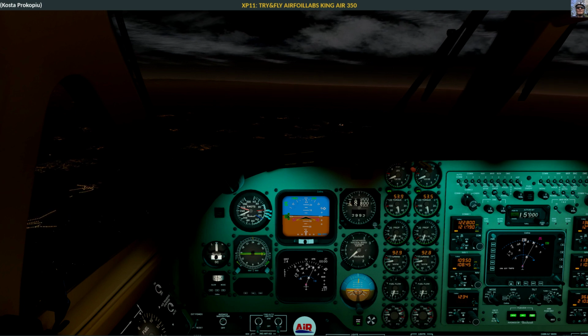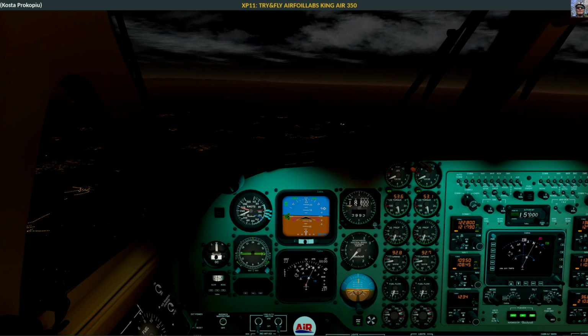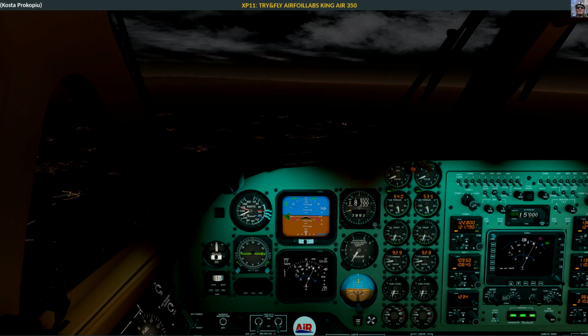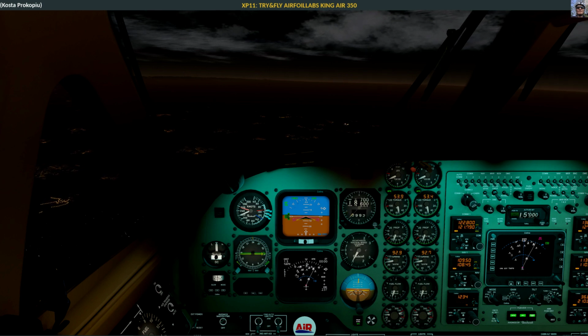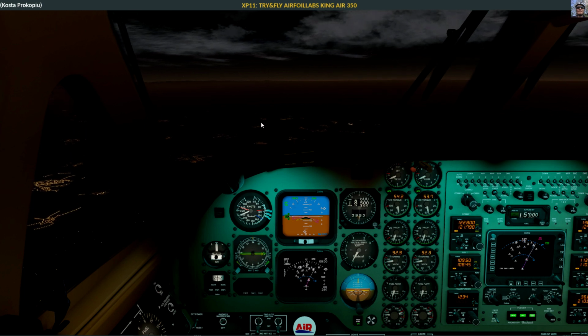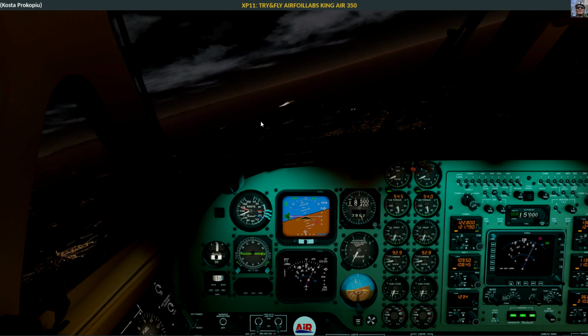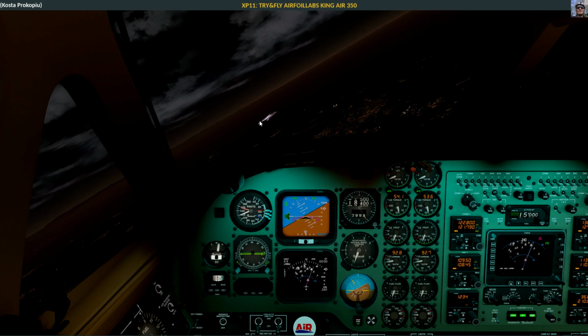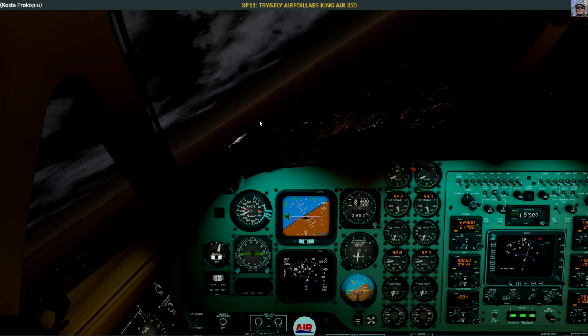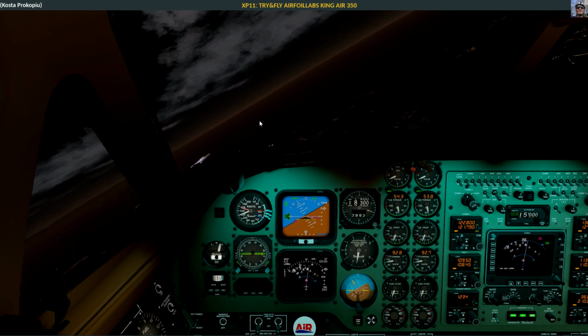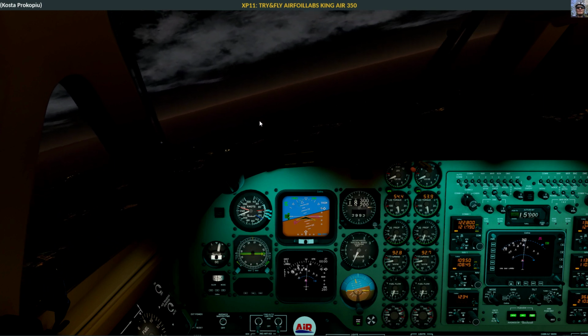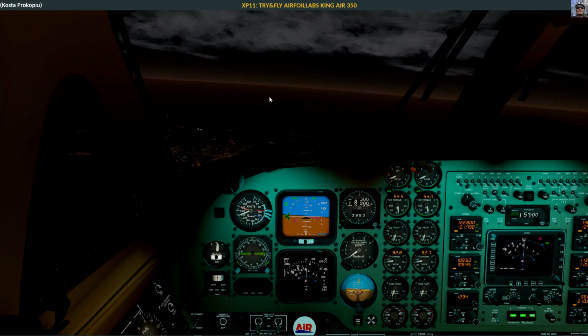And I'm looking at the descent transition checklist now. Descent transition. 29 something, add to airport. Pressurization. No, that's not what I need. So fuel balance check. Auto feather is armed. Ice protection is acquired. Window defog is acquired. Windshield defrost is acquired. Destination weather we know. Approach procedure, recheck brief, cabin sign, consider exterior lights as required, altimeter set. Descent transition checklist completed. Okay.